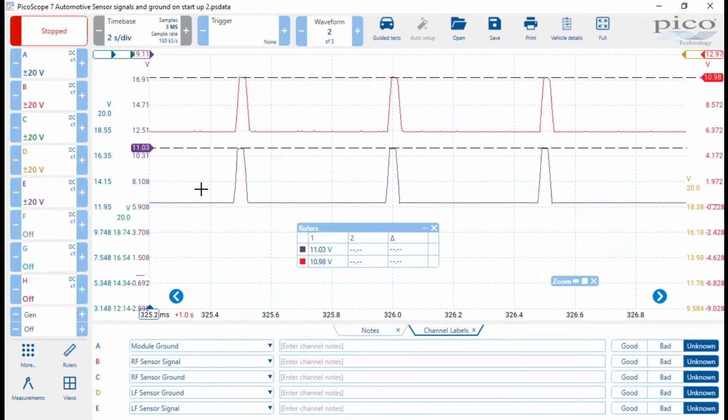Obviously, if there's a difference in signature between the two test points, then I've got a wiring issue between the module and the sensor. Now, if they're the same, that obviously means that the computer's looking at this in a different way than I'm looking at it. I'm looking at it as straight voltage signature. The computer obviously must be looking at something else, because for all intents and purposes, the voltage signature, at least when you turn them on, looks to be pretty normal.